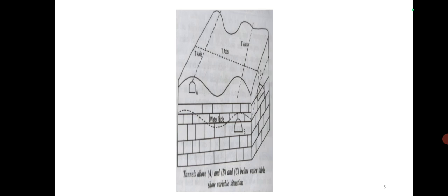So the tunnel will not have any disturbance due to change in the groundwater table. It is well above the water table. If that is the alignment, it is the most preferred, and the disadvantages or unsafe conditions will not arise due to fluctuations in the water table.